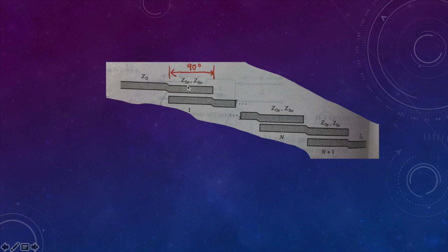The electrical length for one stage is around 90 degrees, and we need to settle down the width of this microstrip line and this microstrip line. Another thing we also need to figure out is the air gap between these two microstrip lines. This air gap serves for coupling the signal from this microstrip line to this microstrip line.